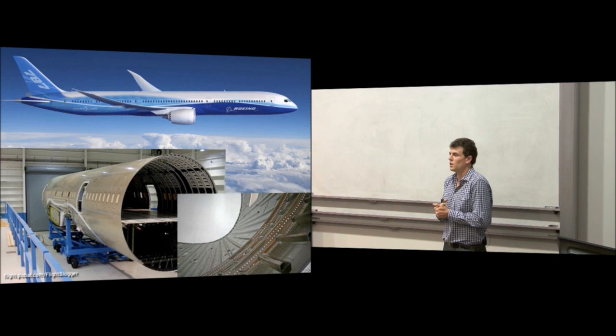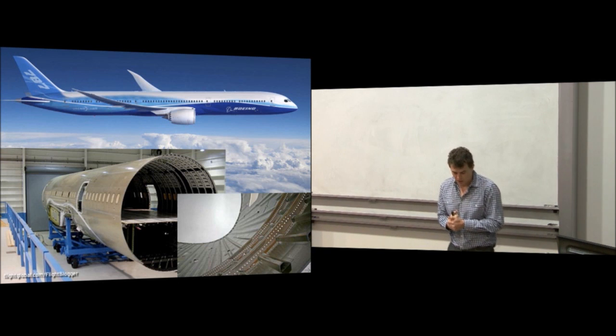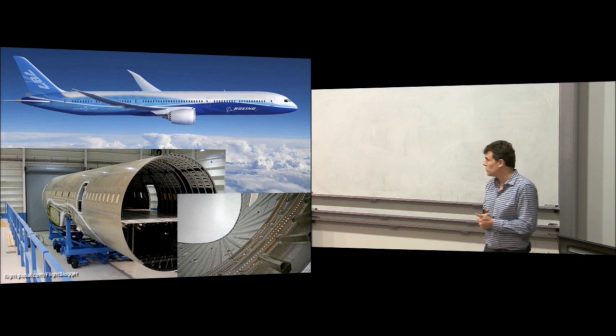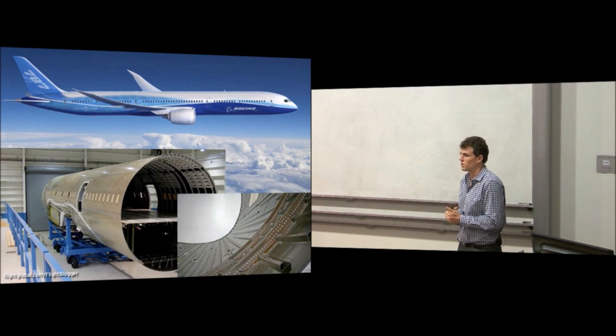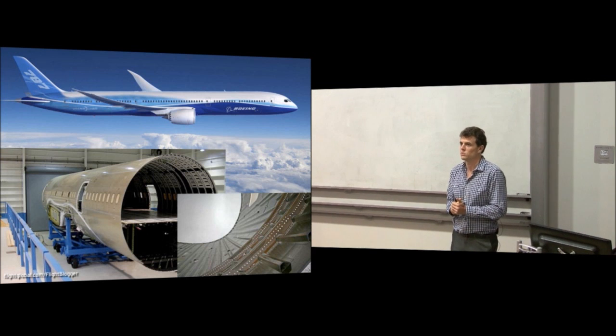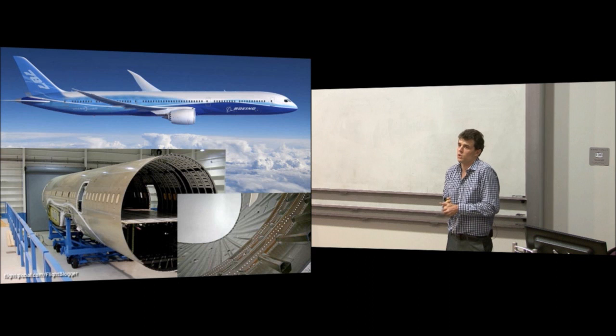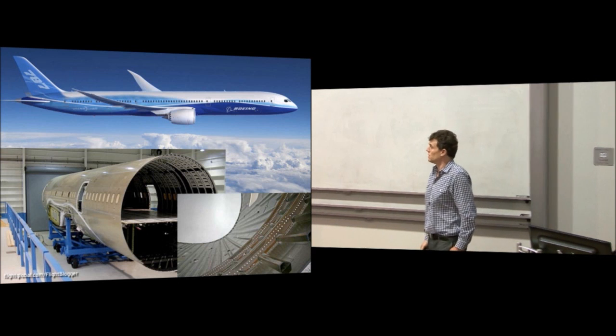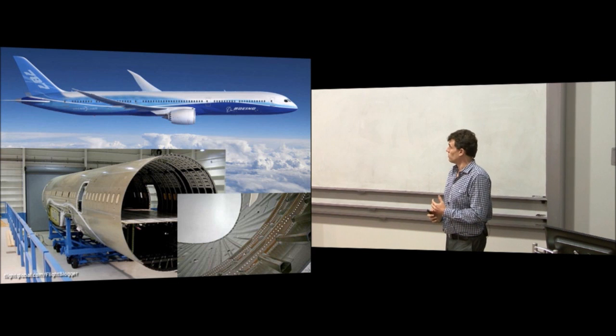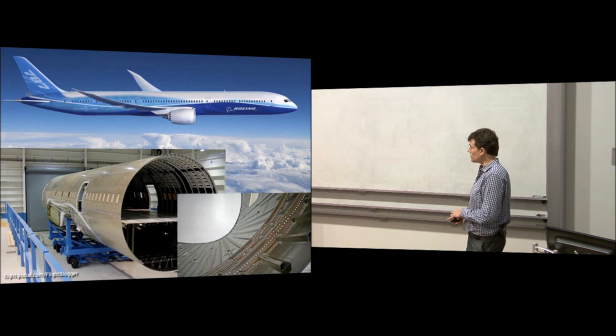Okay. So first of all, the bit that everybody likes about composites is where they're being used. If you've been paying any attention at all to the aerospace industry recently, you'll know that the big famous aircraft that are coming out by the two big manufacturers are moving more and more towards composites all the time. So the 787 was about 50% composite by weight, because as we know now, composites are significantly lighter than most alloys. So when we say 50% composite by weight, we're really talking about 80% of the volume of the aircraft was carbon fibre composite. And this is obviously a 787 up here, one of the nice renderings that Boeing likes to put on their website.